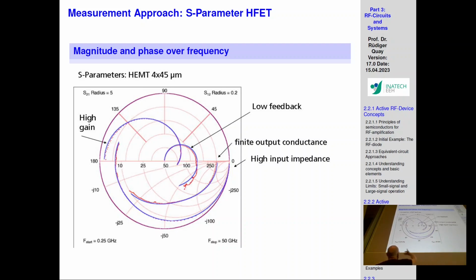As we move along the Smith chart, we're moving towards lower impedance points, and we see that the input matching goes to the lower impedance points. That's why in the other graph the 10 was selected. You can imagine, if you're here with a reference of 50, and there is 10, what is that for a value? Is it 7.5? Is it 7? Is it 6? It's not very easy to distinguish by eye. So if you know that your impedance points will anyway lie in that region, then you take a reference which is closer to that region, and the reference is in the middle, and you have a higher span of values that you can then more exactly say, oh, that is at 7.4, the other one is 7.3, and so forth.